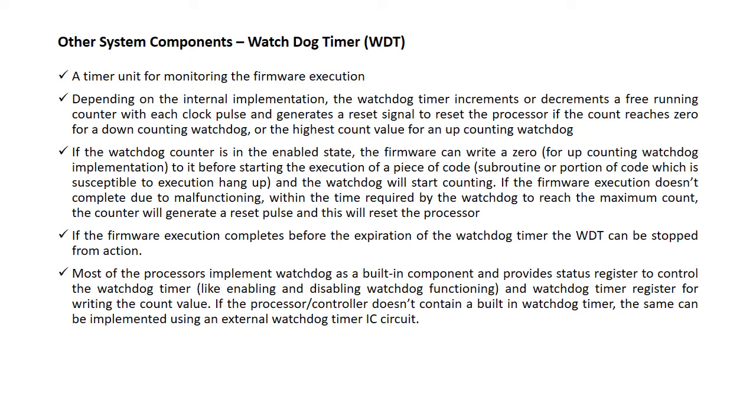If the watchdog counter is in the enabled state, the firmware can write a 0 for up counting watchdog implementation to it before starting the execution of a piece of code, subroutine, or portion of the code which is susceptible to execution hang-up, and the watchdog will start counting.